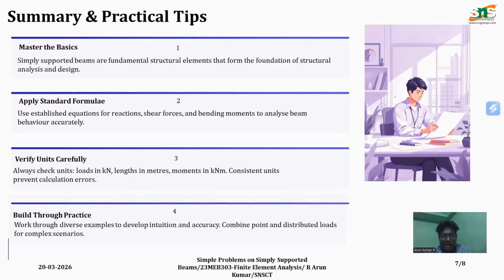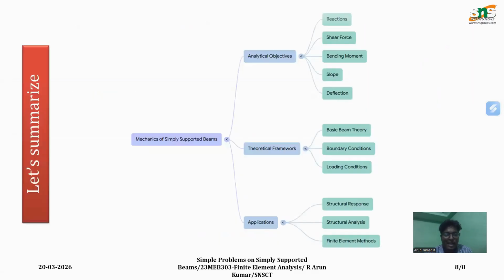Verify the units carefully. Always check the unit of load in kilonewton, length in meter, and moment in kilonewton meter. Consistent units prevent calculation errors. Build through practice: work through diverse examples to develop intuition and accuracy, combining point and distributed loads for complex scenarios.